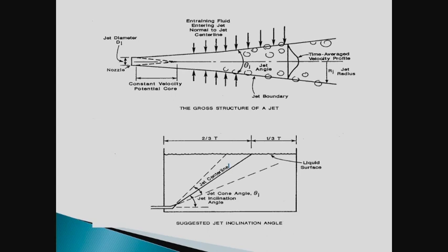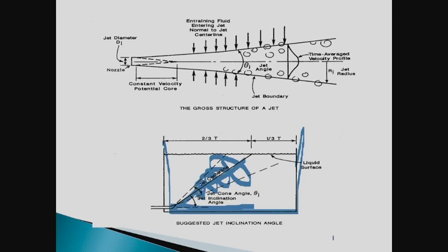jet mixing is particularly useful for very large storage tanks. So you have a very large storage tank, maybe this is 40 feet in diameter, whatever, and you do not want to have the jet along the tank bottom. What you want to do is have the jet fully expanded and expose the surface area to the mixing. So this is the type of thing, it may be 2 or 3 days before you get that tank mixed up. Of course, the bottom is, again, a particular area.